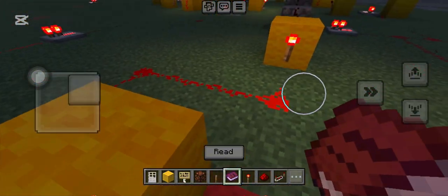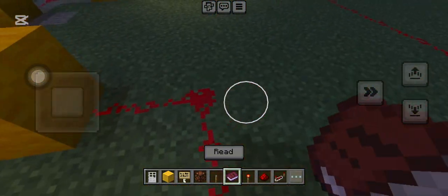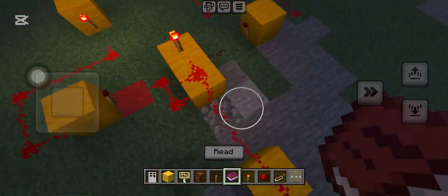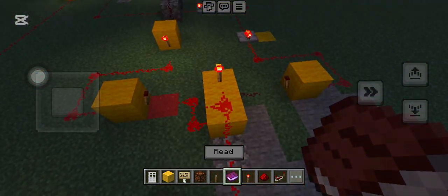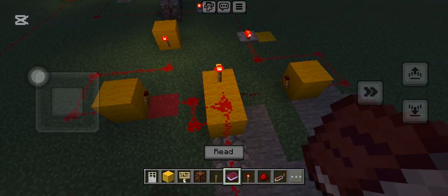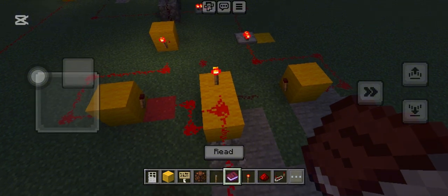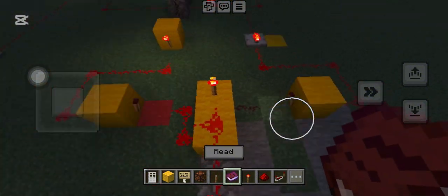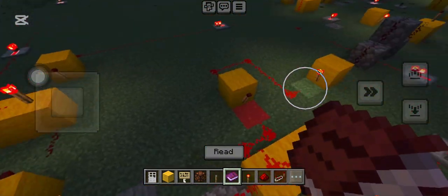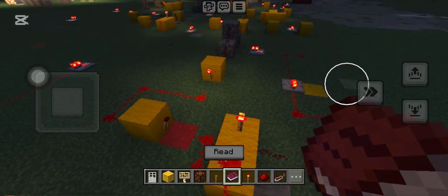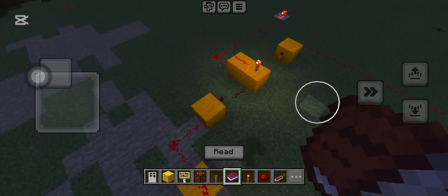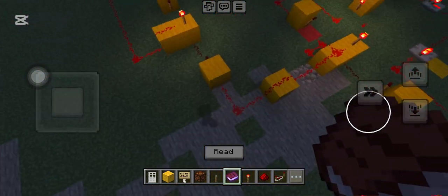The next part we also have an XOR gate. It's combined from the OR output with the NOT AND output. The XOR gate just turns on only when the partial sum and the bit 1 carry are different. And that is our real final bit 2 sum. So we now have the final bit 2 sum and the bit 1 sum.